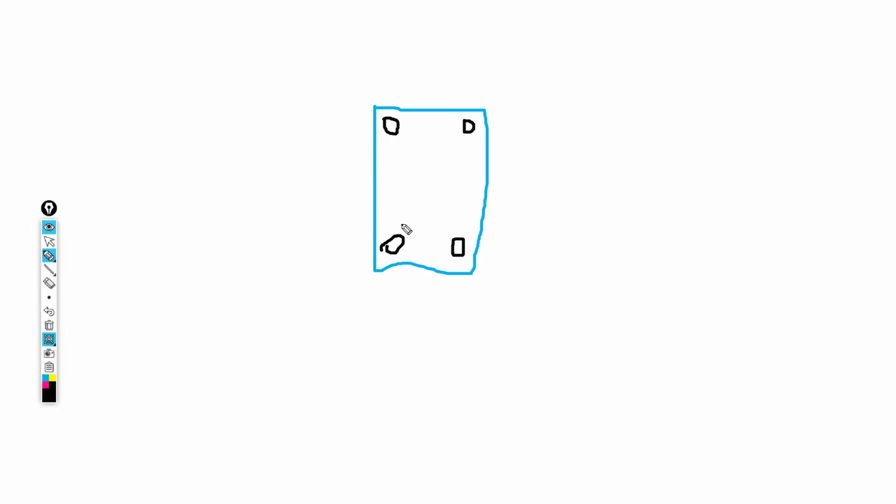But then if the program finds out that these bars are not enough, and maybe you need 5 bars, usually those additional bars are either at the bottom of the beam, because that is where you expect tension, or at the top of the beam.